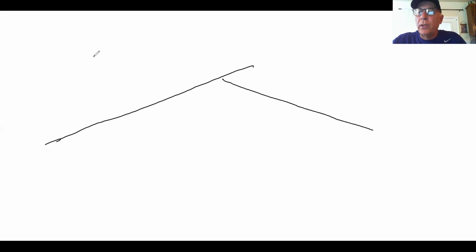So I'm going to go into the draw package here, and I am going to draw the curve coming in. Again, remember, this is our PI point right here. We know that we have a tangent distance coming down here, which is going to define our PC. And then we have that same distance along there, which is going to be the PT. So again, remember this point is our PC, our PI, our PT.